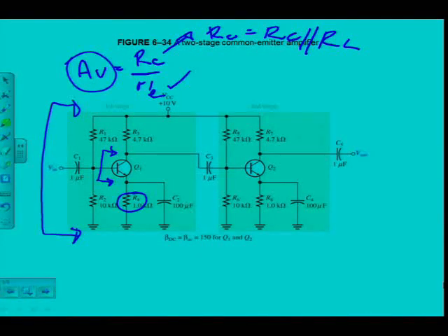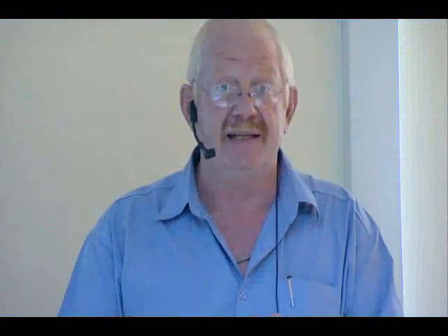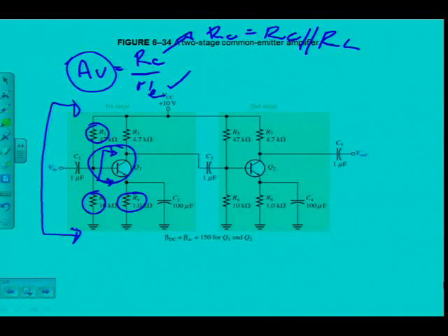Alright. Then we didn't stop there. I had to calculate Rin total. You remember? Rin total was of course R1 parallel with R2 in parallel with Rin at the base. Then I got Rin total. So if I ignore this first stage, you agree that I would do the same for the second stage. I would work out Rin at the base.